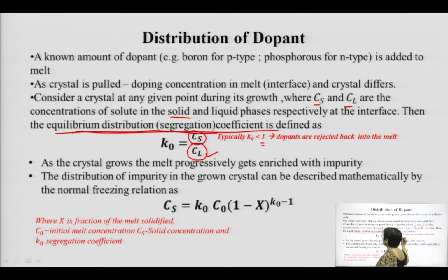is increasing as the crystal growth process happens, except for oxygen and carbon many times. For some applications, you try to keep it this way. As the crystal grows, I told you the molten silicon is enriched with impurities. That means, at first, when the process starts, you will have pure crystal. As the growth process happens for a time interval t, your impurity addition into the single crystal will keep on increasing